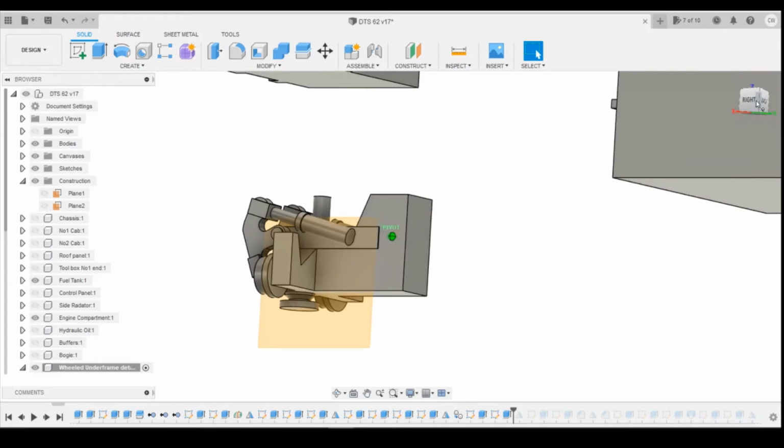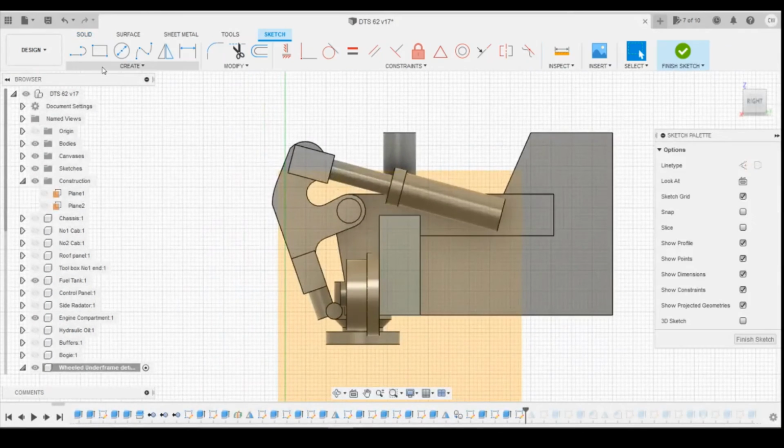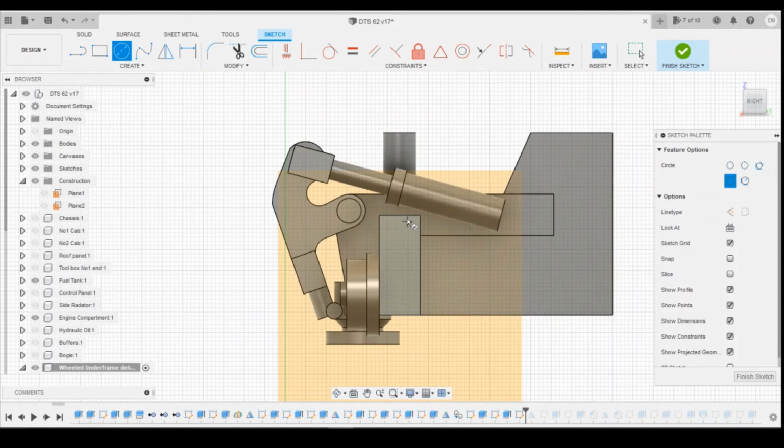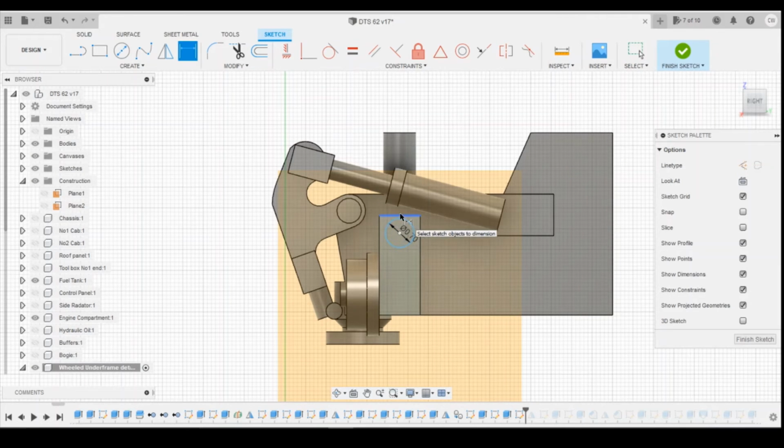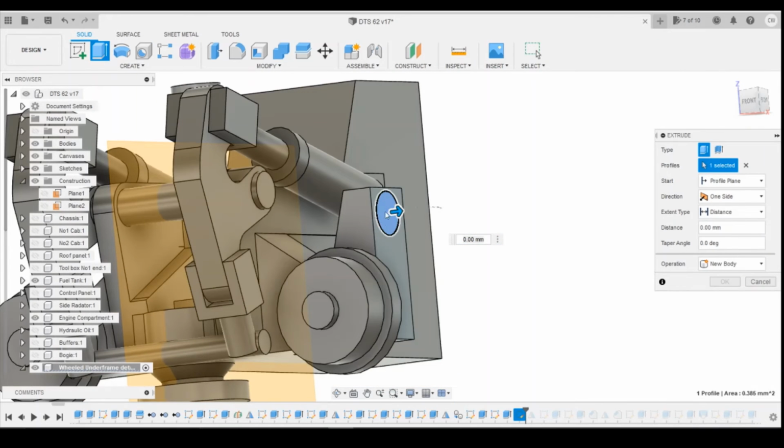Back there, I'm going to draw on that surface 2 circles. In fact I'm going to do 1, because then I'm going to copy it downwards, or pattern it. I'm going to go for 0.7mm thickness, define its height from the top surface, 0.4. I'm going to extrude outwards. I'm going to come 1mm, tell that to join.